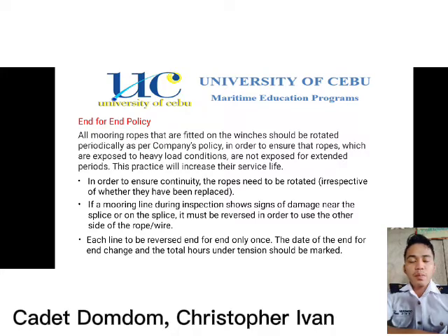Next is the end-for-end policy. All mooring ropes that are fitted on the winch should be rotated periodically as per company policy in order to ensure the ropes which are exposed to heavy load conditions are not exposed for extended periods. The practice will increase their service life.